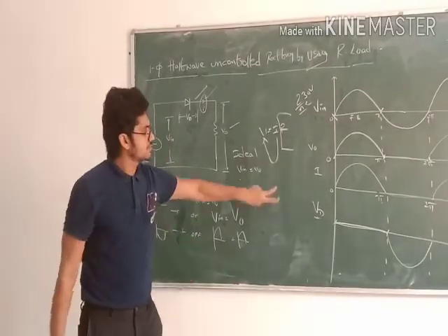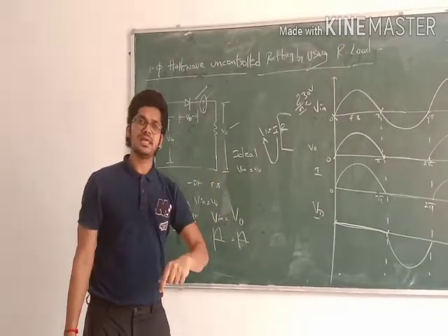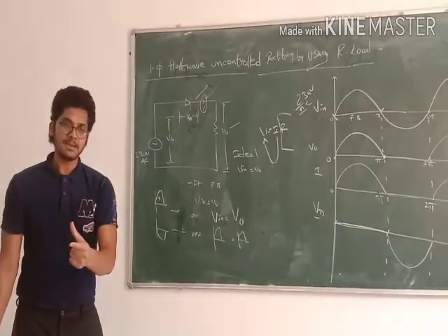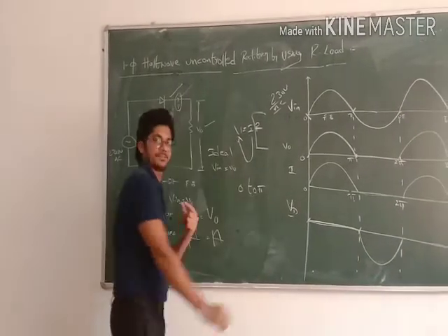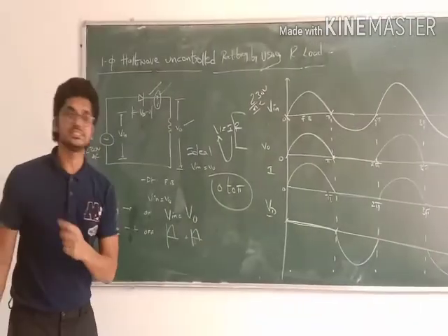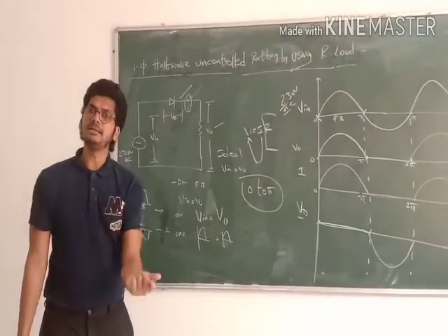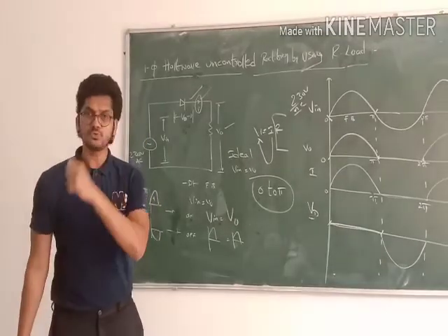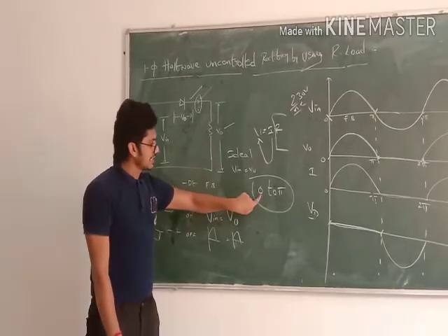Let's assume that by using this circuit, I convert the AC supply into the DC supply by using the concept of the single phase half wave rectifier with the R load. Here, the conduction angle of my diode is 0 to pi. Because with each load the conduction angle is going to change. With the R load, my conduction angle is 0 to pi. With an RL load, it can change to 0 to pi plus sigma. For another RL load, it is going to change again.